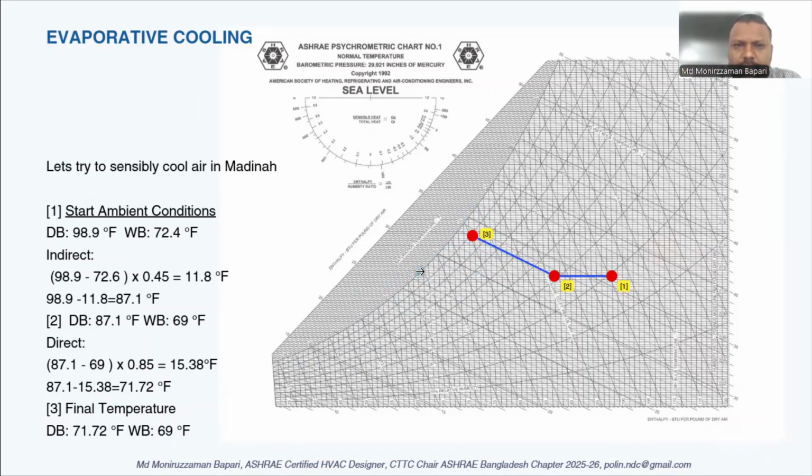Evaporative cooling is particularly efficient in open spaces. If we continuously do evaporative cooling in closed spaces, spaces that are not so big, not like a warehouse, in a very small space, the weather is going to be hot and muggy. Sometimes it is unbearable. Again, you need to check this with ASHRAE 55, the human comfort zone.